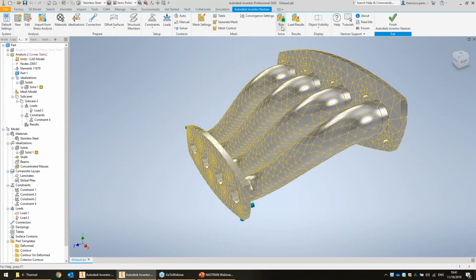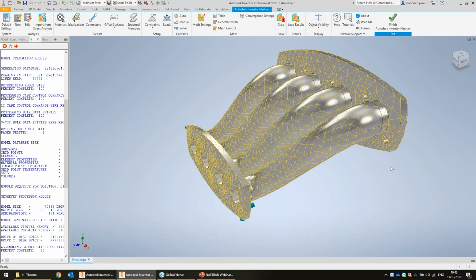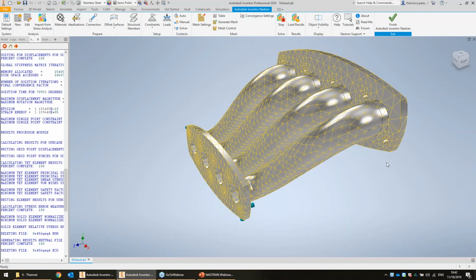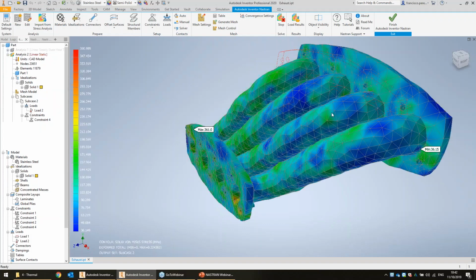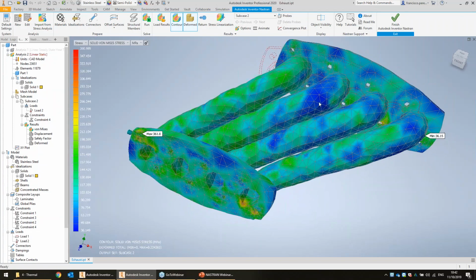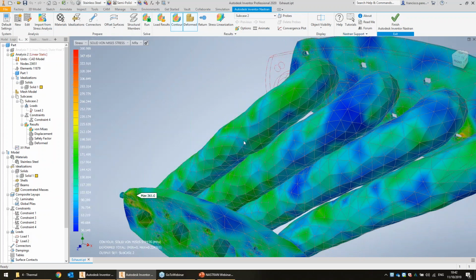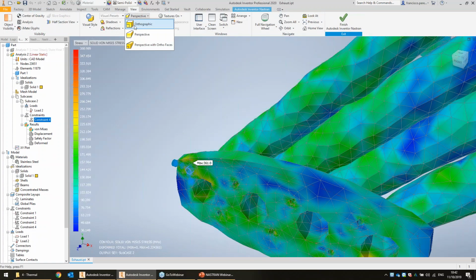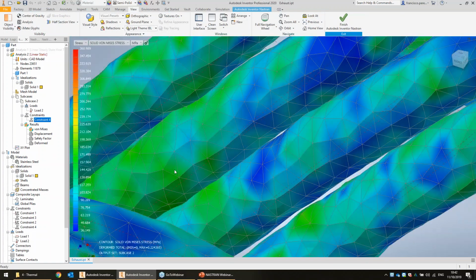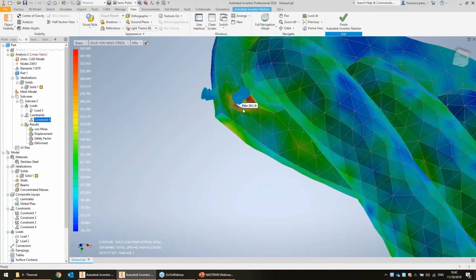There we go. This mesh could surely use more refinement, but we're going to continue anyway. So what it's doing at the moment is grabbing the output of the thermal study and inputting it into the linear static study. And here we can see the subsequent stress as a result. Now we can say, and rightfully worry, that we're getting significant deflection in that direction because it's expanding. And we can see also, oops, go to view and orthographic. Here we can see a significant von Mises stress in that little lip where the fastener is coming in.